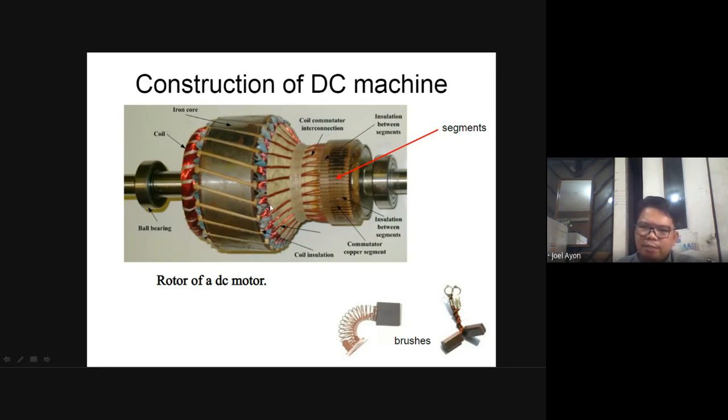But there are some DC motors, as I've mentioned, that are the disposable type. Once the brushes wear out, you throw it away, because in the design the housing is not bolted but riveted, so you can no longer fix it. Any questions so far? None so far.